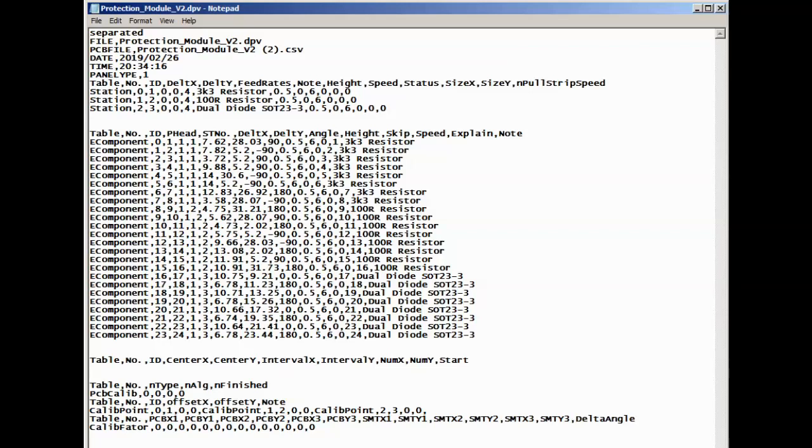So the way the pick and place machine works is you essentially give it 2 or more calibration points, and then it will interpolate all the intermediate positions to determine where each component lays and needs to be placed. We'll look at this in more detail when we get to the machine, but just bear in mind that it's a good idea to include some calibration points on your PCB design, and again we'll look at that later.